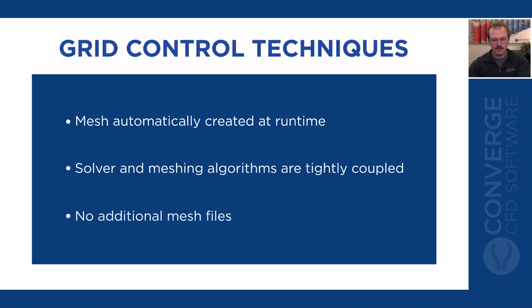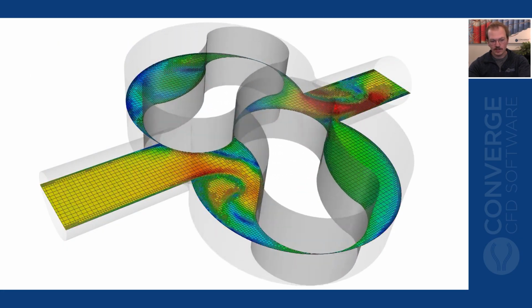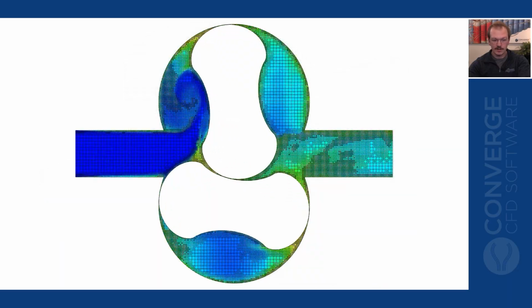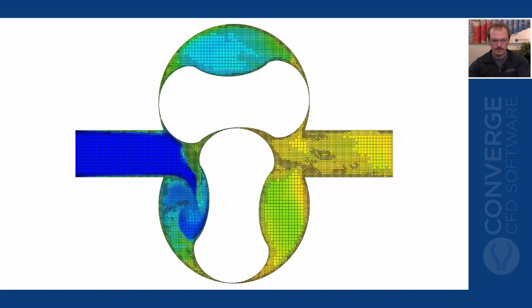Unlike other CFD codes, CONVERGE maintains the original surface definition with high fidelity. This means that the volumes and areas are correct regardless of the mesh resolution. And while the mesh is created automatically, you still have full control over the size of the mesh.